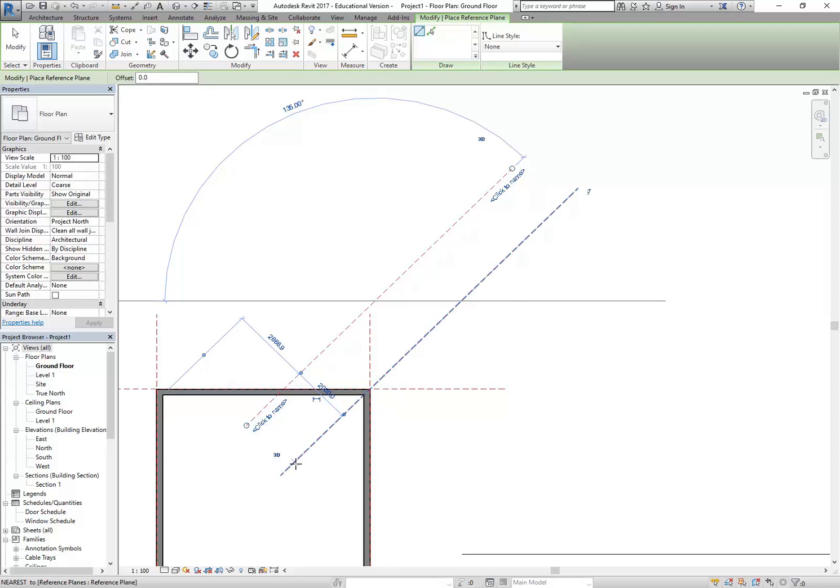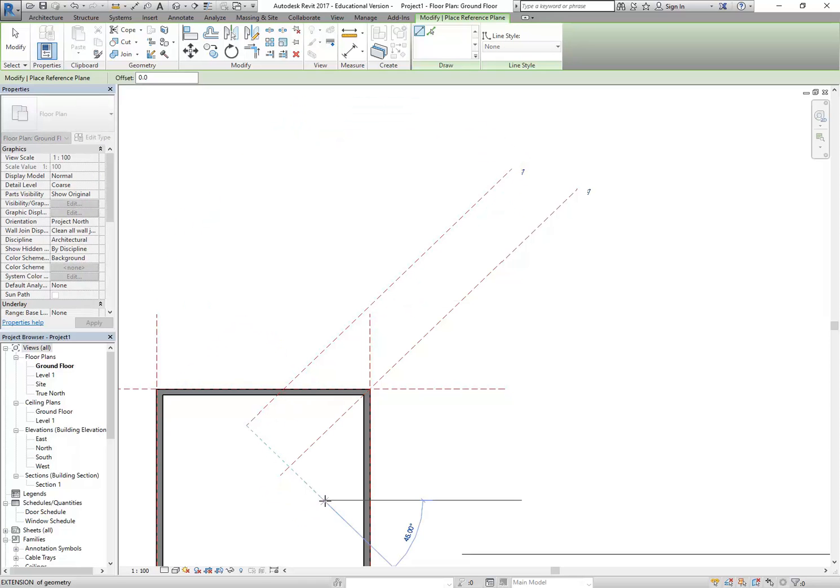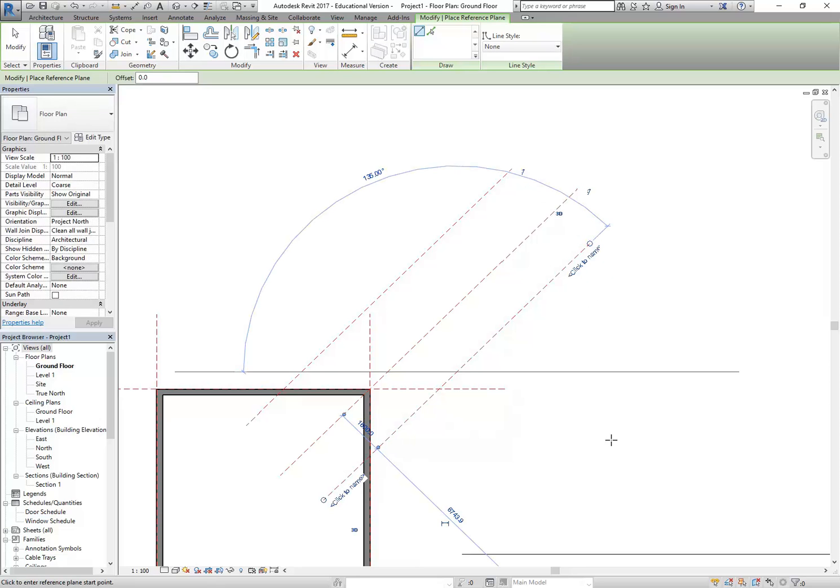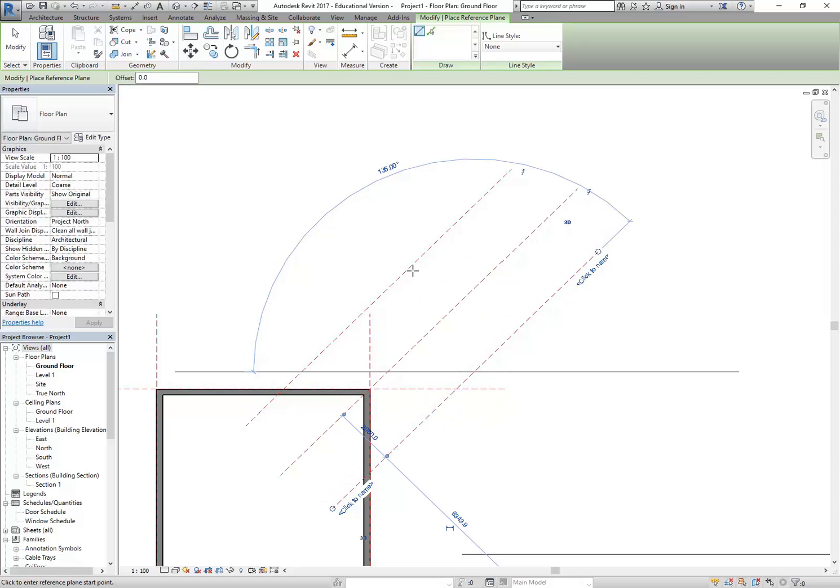And if you've done that, that's the right idea, because we want it to be 4,000 altogether, so I'm going to draw a new plane now, starting inside the building again, going up and to the right, also at 45 degrees. So again, being careful to get the angle, not worried about the distance, because now again I can make that 2,000. So I've got 2 reference planes either side of my centre line, and I know because it's 2 metres either side that it's 4 metres between those.